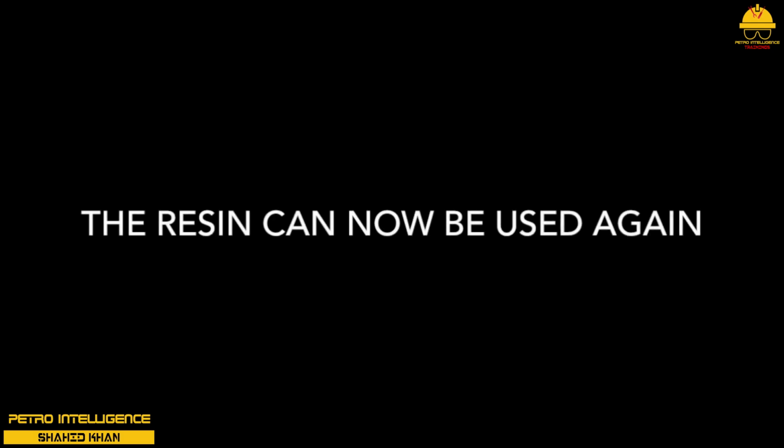At this point, the bed is said to be saturated, and it must be regenerated before it can be useful again. Regeneration is the restoring of the original ion to the surface of the resin beads. In the case of the water treatment resins, the bed could be soaked in a concentrated solution of sodium chloride, replacing the hard metallic ions with fresh sodium ions.